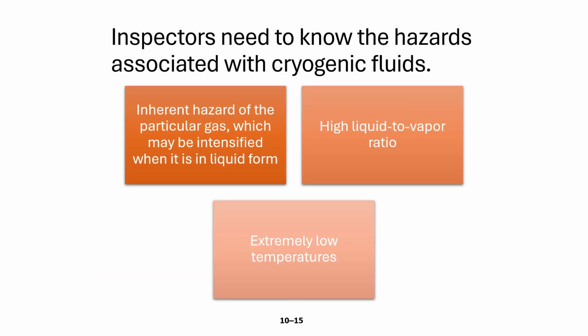In essence, the hazards associated with cryogenic liquids fall into three categories. You've got the inherent hazards of the particular gas, which may be intensified when it's in its liquid form, high liquid to vapor ratio, and extremely low temperatures. So the inherent hazard of liquid oxygen, that oxidizer in that state, means there's more of it if it's exposed to some sort of fire event.